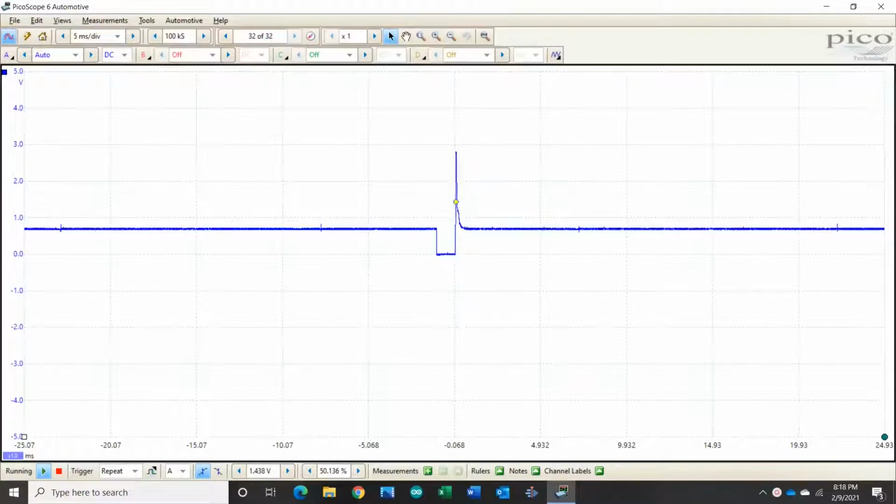Okay, so now that we have the waveform a little bit more steady on the screen, let's take a look at the voltage scale. Like mentioned previously, the voltage scale is on the y-axis, and the blue numbers here correspond to the blue waveform. That's important to know because once we add other channels in the future making voltage measurements at the same time, the color of the number on the voltage scale corresponds to the color of the actual waveform itself.